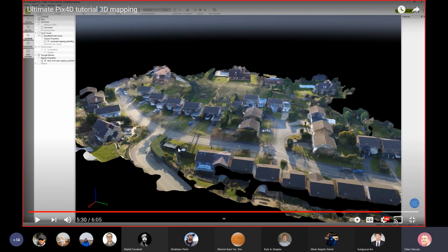The next step is you take your drone, go to the site, and you place your drone, as mentioned in the video, in an area where there are no trees or maybe power lines close by. I'll let you know later on. Then once you pick this point, you start your mission. The app will completely control your drone. It's autonomous, so it means the app will send your drone to the right elevation.